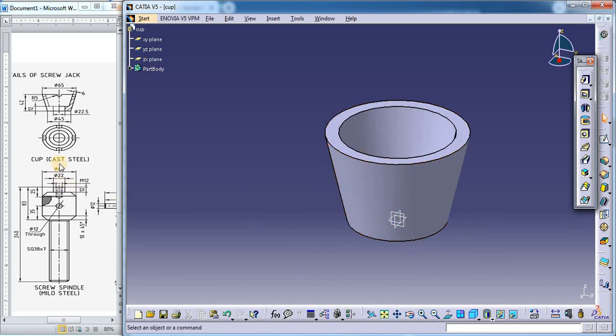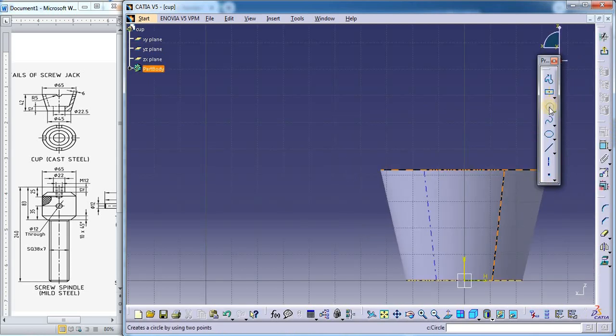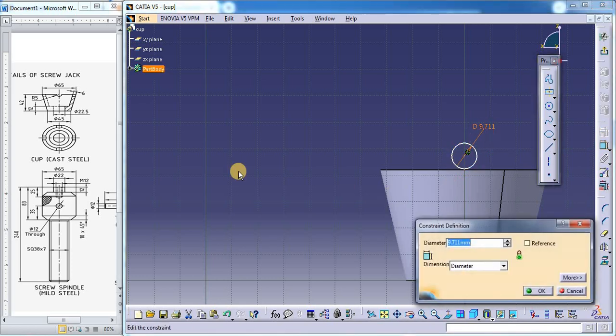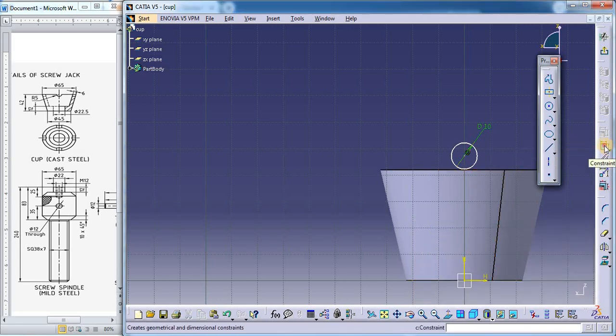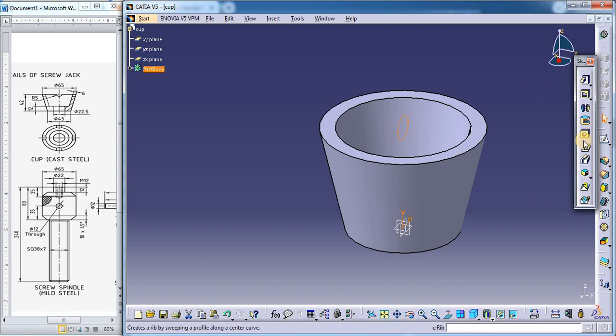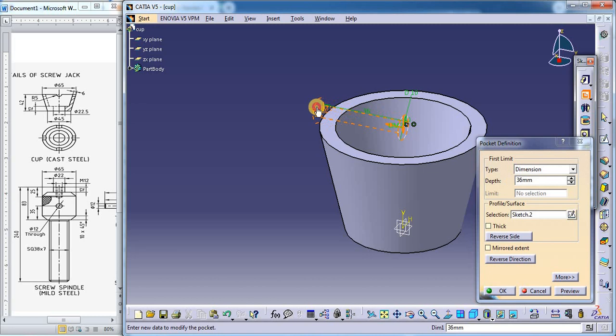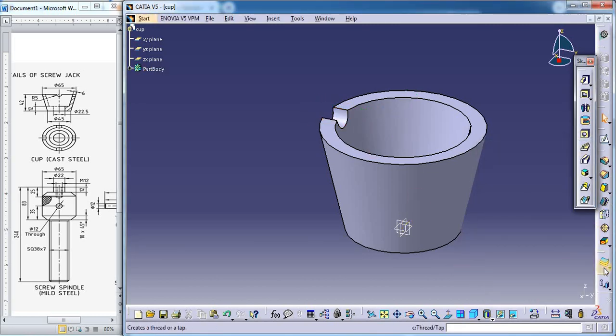So here you need a cutout here. So click vertical plane and go for sketch again. Draw a circle on the origin, in the sense a vertical direction origin, and then give a diameter to it of mentioned as 5, then diameter becomes 10. So from this point to this, we make it coincide. Exit from the workbench. Here select pocket in this direction.